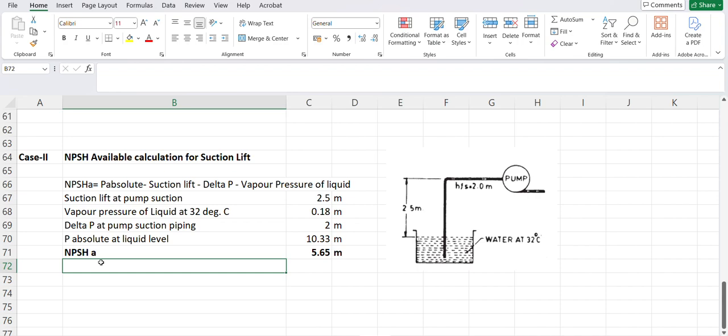Cavitation happens when the NPSH available is on the lower side, which could damage the casing and pump mechanical seal, create abnormal sound and noise, and affect the pump performance as well as efficiency. Hence this is the most important parameter to consider while sizing or designing centrifugal pumps.